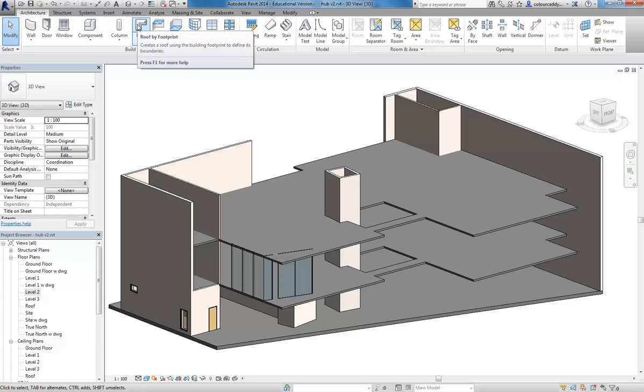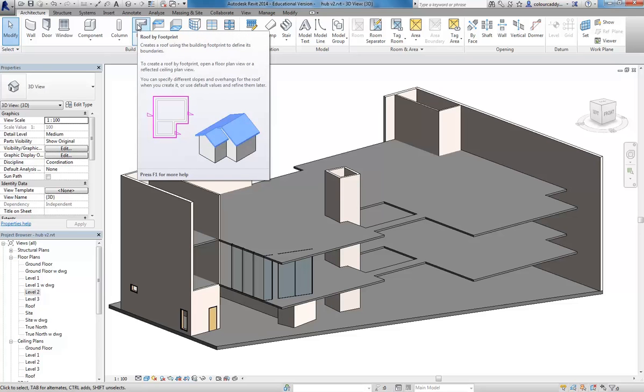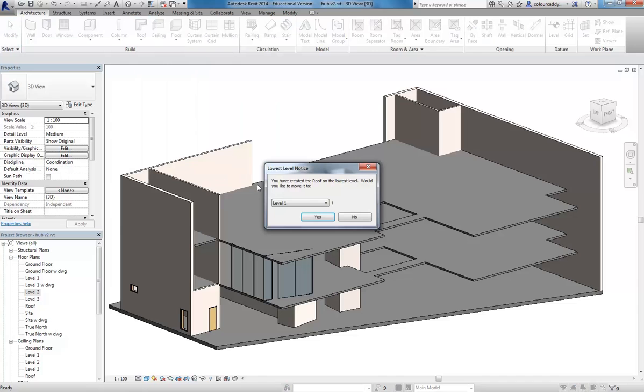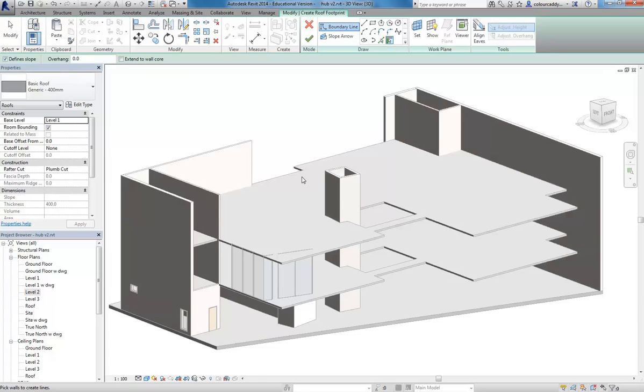Have you used the roof tool much in Revit? No? Don't be afraid to use it, because once you can use the floor tool, you should be able to use the roof tool. Basically the same. Just going to show you one option. Turn define slope off though. Just turn that off. Mostly, I don't think any of you have, or many of you have sloping roofs. If you do, let me know and I'll show you what to do there. But if you've just got a flat roof, just turn that off and you should be away.